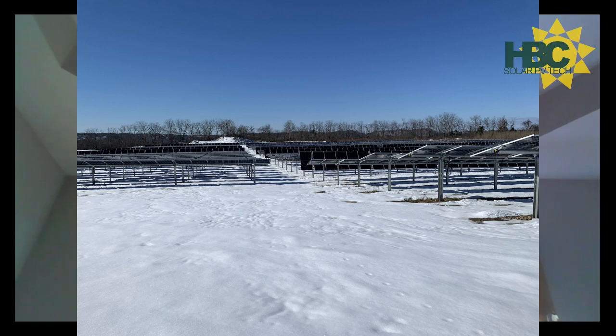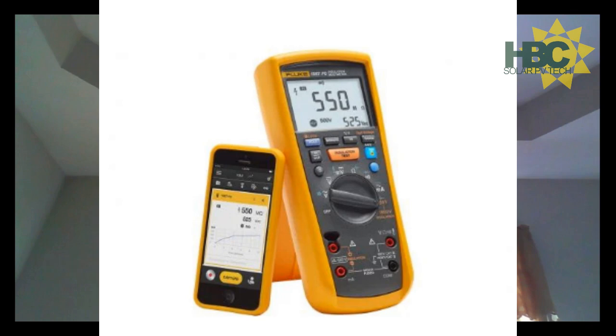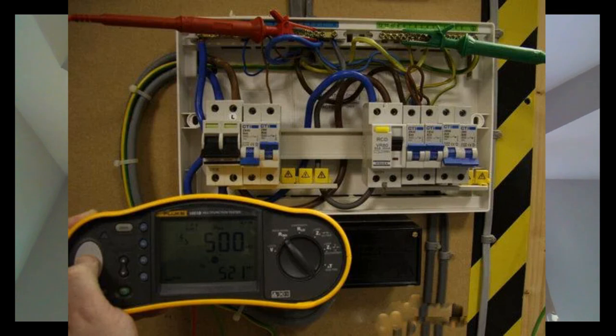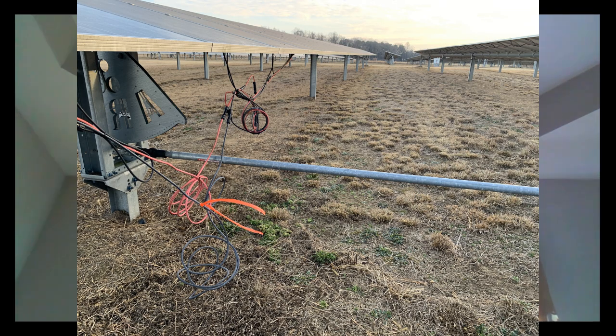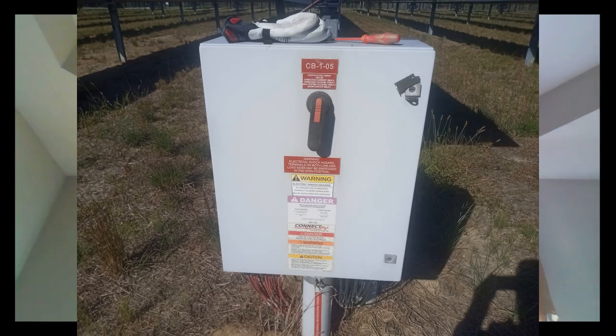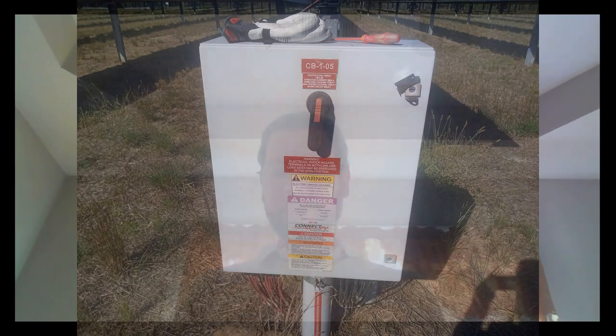In larger PV systems, you may not know which section of the array has the ground fault. One way to narrow the search is to use an insulation resistance meter, like the Fluke 1587 FC insulation multimeter or the Fluke SMFT 1000 multifunction PV tester. The meter can help you identify a subsection of the array with lower than normal ground resistance. For example, in utility scale systems where multiple combiner boxes are connected to a large central inverter, the data acquisition system may not identify which combiner box has the ground fault.